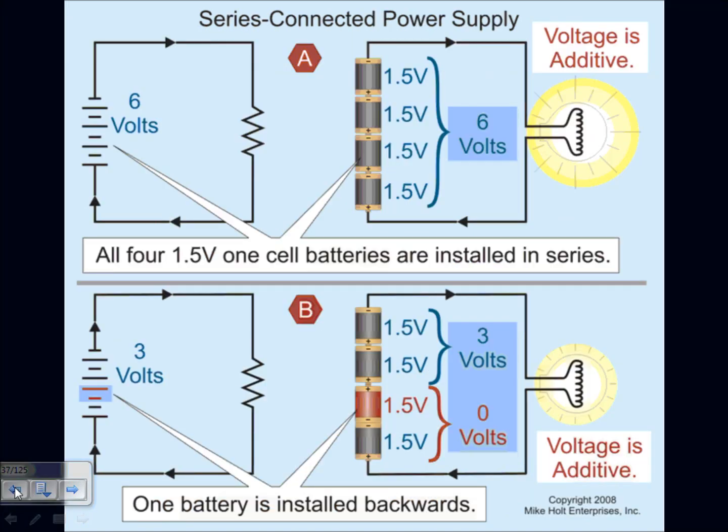Okay. I don't know how many of you guys have looked at this and said, Chad, are you kidding me? You're showing me sources of power in series. There are two ways, guys. Remember the loads, you can put the loads in two ways, either in parallel or in series. 99% of the loads are in parallel because the voltage stays constant for them. They are made to work on a constant voltage. Now, the sources of power, you can put them in series and parallel.